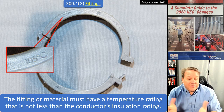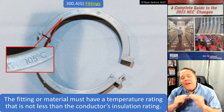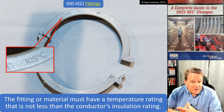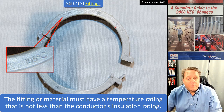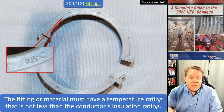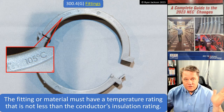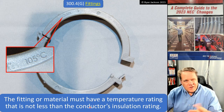It's one that I never really thought about until I really sat down and read it. It says the fitting or material must have a temperature rating that's not less than the conductor's insulation rating. I never really thought to look at a temperature rating on a plastic bushing like this, but most everything has a temperature rating. So this thing is rated 105 degrees C, so we're going to be in the clear putting that in. Probably need to make some changes in the 2026.